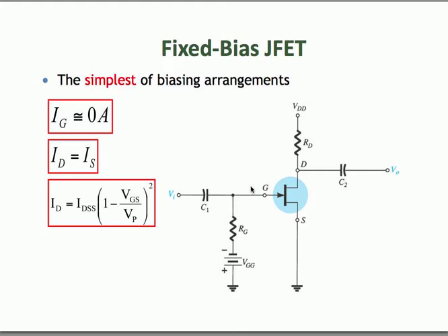For this arrangement, the gate current is zero, the drain current is equal to the source current, and the drain current is given by the Shockley equation.